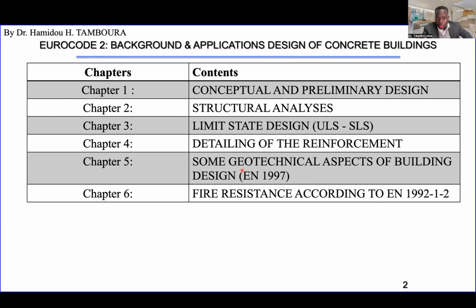As you know, when you apply load on the footing, for example, there will be reaction of the ground. The ground will react on the footing. You need to design your footing so that it can stand the reaction of the ground and also the load coming on it. So we will talk about some geotechnical aspects in this chapter 5, and this is a little bit related to Eurocode 7.